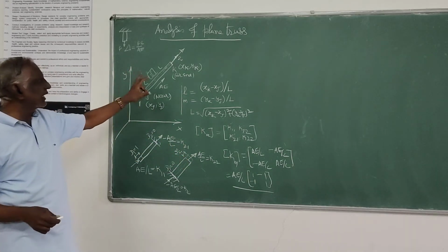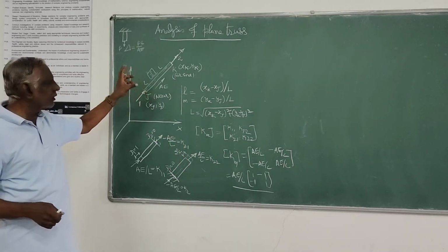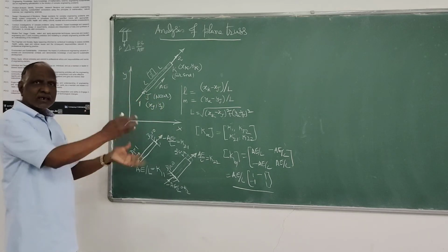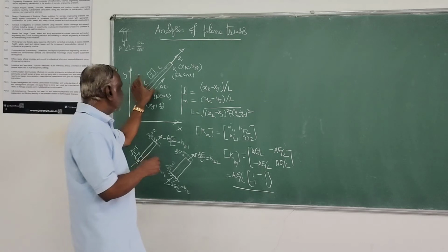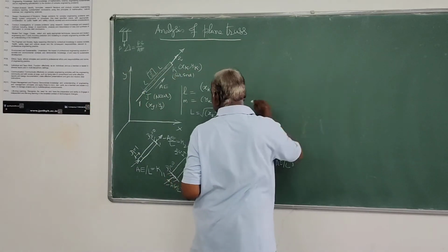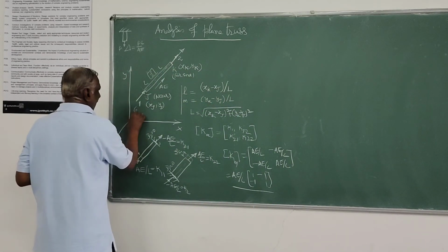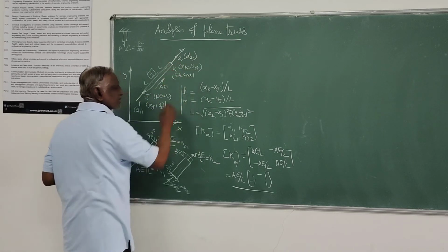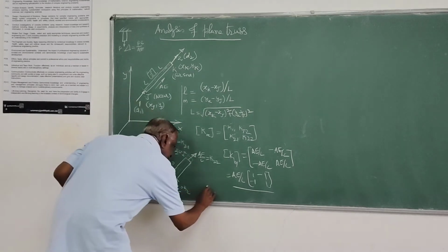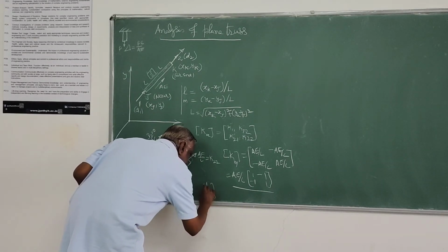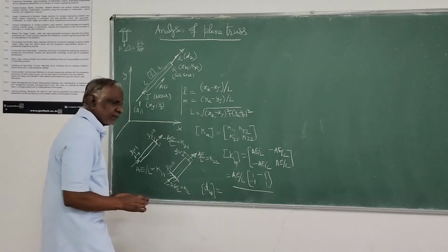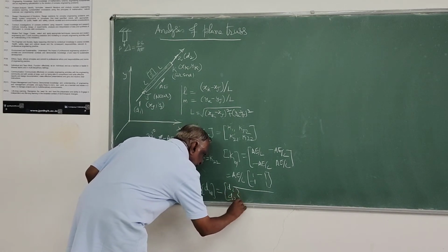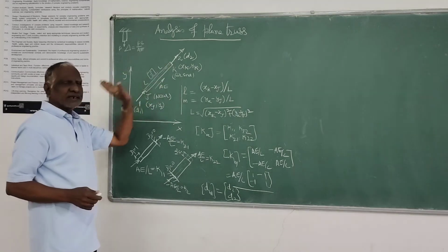That is, we derive an expression for global stiffness matrix as well as a local and global displacement relationship. The same element, and of course here I will call the displacement d1, here displacement d2, and the member displacement small dm is always this d1, d2, that is dm1 and dm2.